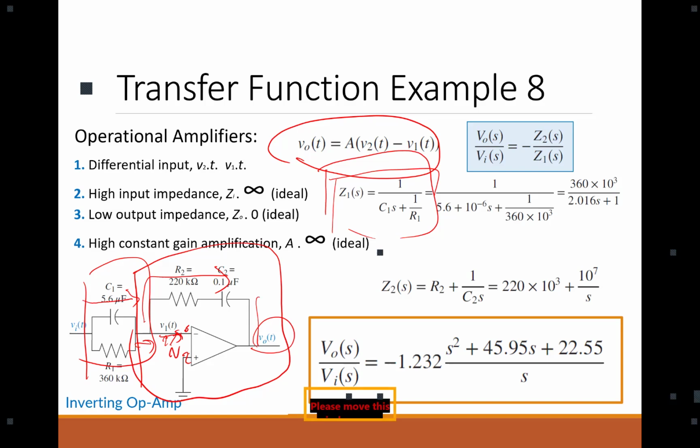This is V2. Okay, so VO here is going to be connected to here. Here also you have a voltage terminal, AB. Are we good? You run the KVL. If you run the KVL, you simply have two series impedance. You know how to do that, and you know how to relate the current and the voltage. So simple KVL gives you the relation between the output and input.